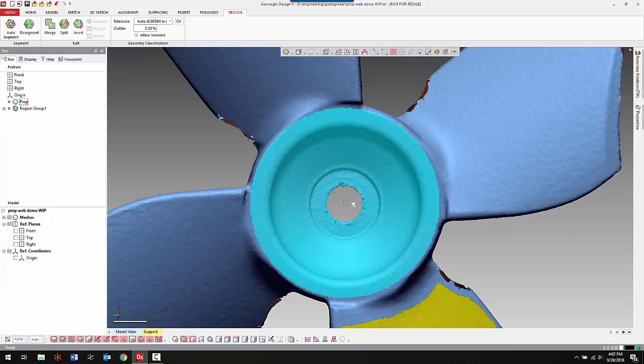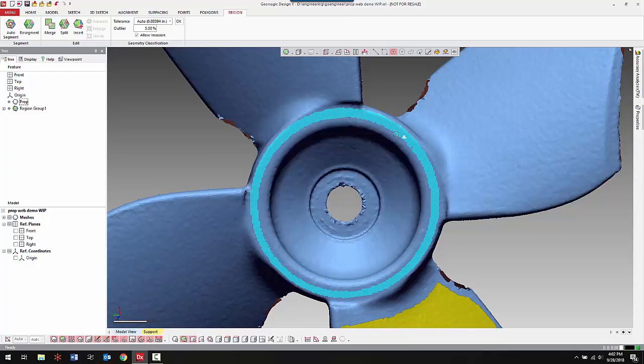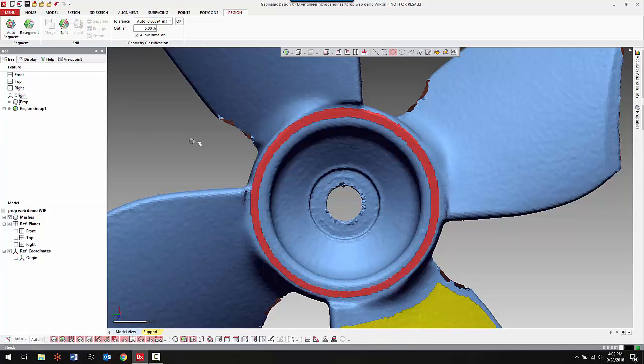And I'll go ahead and do this again, and this time I'm going to remove the inner selection. And what I'm looking for is just kind of a ring around that flat surface. So I'm going to say Insert. And I'm going to verify by coming back over and touching that region to confirm that it sees that as a plane. So now I can create a mesh sketch